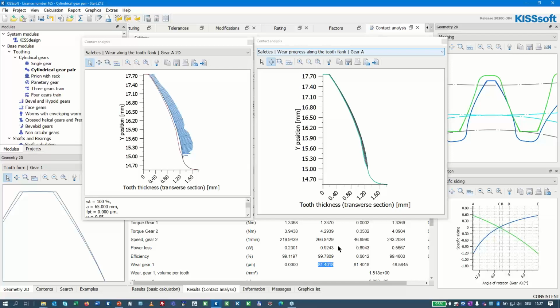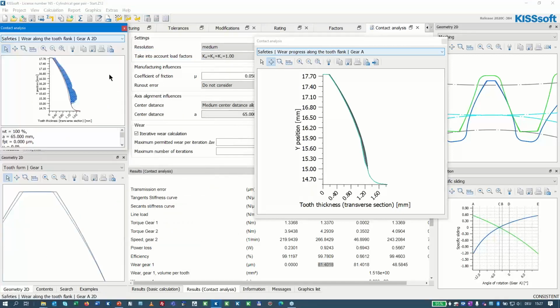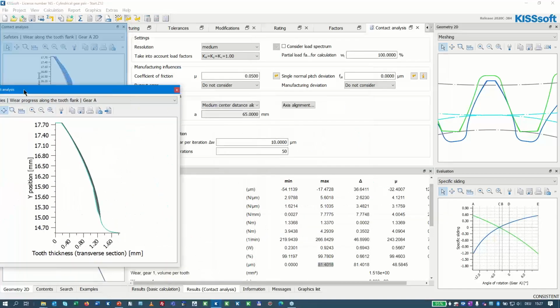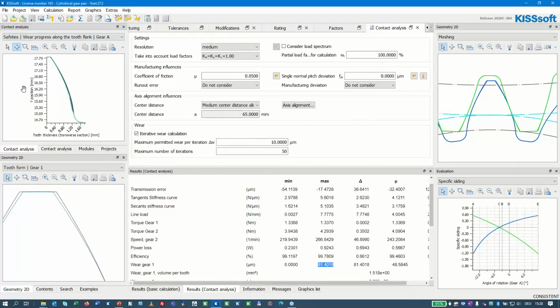Now let us say, for the sake of argument, that the flank optimization is now completed. We are happy with the flank, and we now move on to an optimization of the root. If we look at the root area here, we obviously see that the root rounding is not maximized. We could inscribe a larger radius, thereby reducing the stress level.